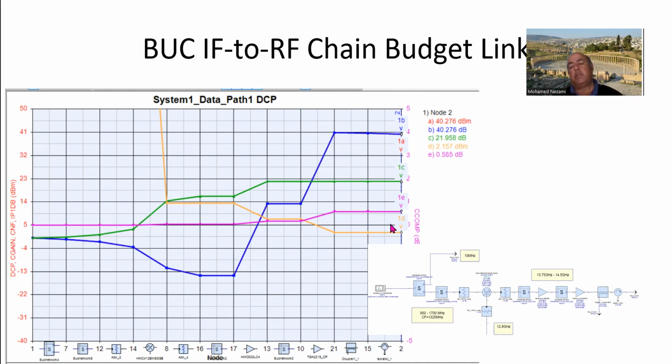By the way, the GaN devices, usually they're most efficient when they're compressed a few dBs into compression. But in that case, of course, if you're doing digital communications, the EVM will be high. And so some people resort to pre-distortion, linearization, whatever, but we chose to back this device off. It's a 24-watt device. We chose to back it off. So the compression here, you can see this compression value is only 0.5 dB into compression at this stage here, okay? Now, the noise figure is a little bit high.